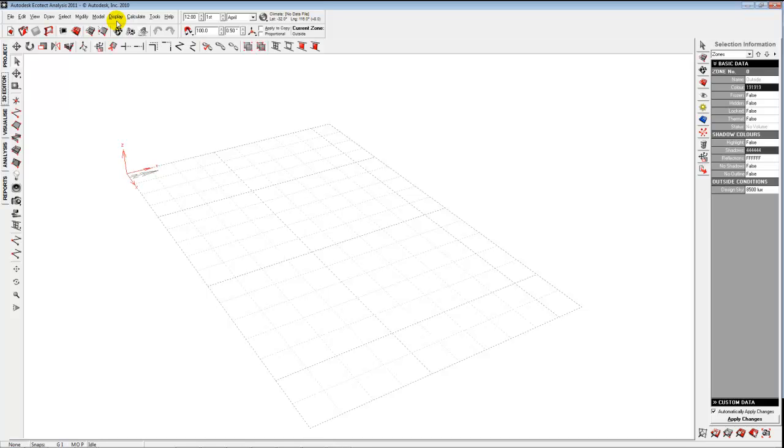Okay, let us take a look at what it is. Ecotect is a very basic modeling environment which has very primitive modeling tools, but really focuses on the analysis side of things. It is really the best tool available today in terms of getting accurate data back from solar radiation, daylighting. It has a very strong analytical engine behind it. And just so you know which engine is behind it, it's the DOE, Department of Energy 2.2 engine that really drives a lot of the analysis that goes on here. It is really rock solid on the analysis side.